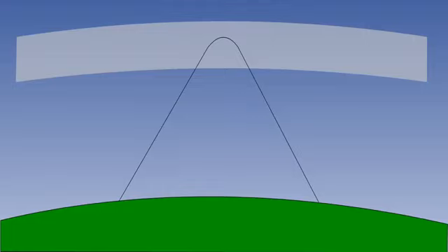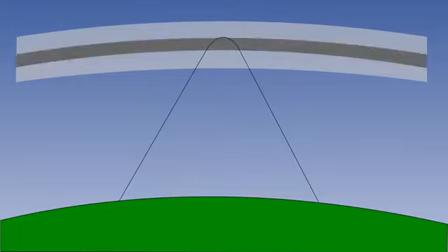When a radio wave is transmitted into an ionized layer and it returns, it is called a sky wave. The refraction or bending of the wave occurs because there is an abrupt change in the velocity of the upper part of the radio wave as it strikes this new medium of plasma. The ionosphere layers are less dense, with electrons at their outer edges, so it is at the center of these bands that the greatest refraction occurs.